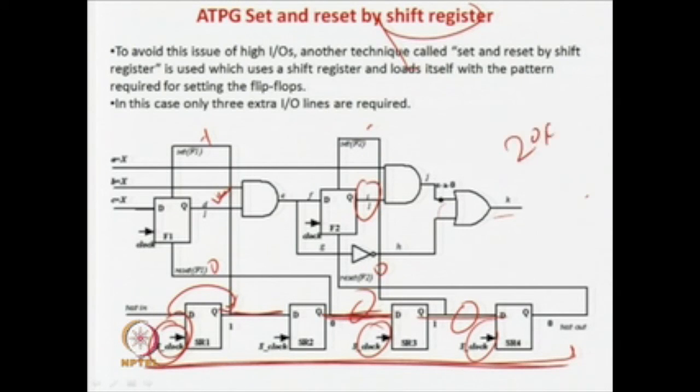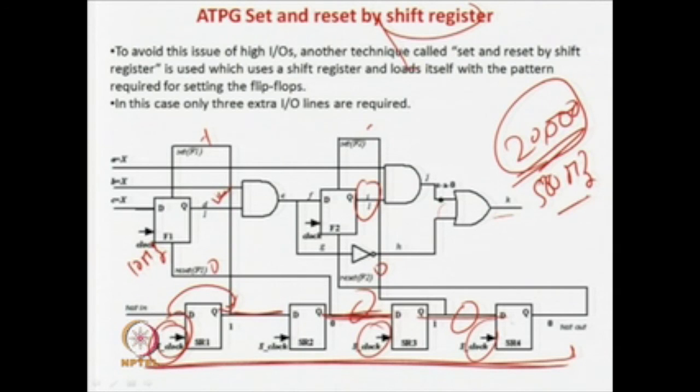So, even if you have to say, for 10,000 flip flops, 20,000 patterns to set or reset these lines, your problem is not high, because if it is say a 10 megahertz clock, you can use it at a 500 megahertz clock or something like that. Generally you can also use a gigahertz clock over here and very quickly shift the data, but this will be slow because there is a lot of combinational delay in this case.